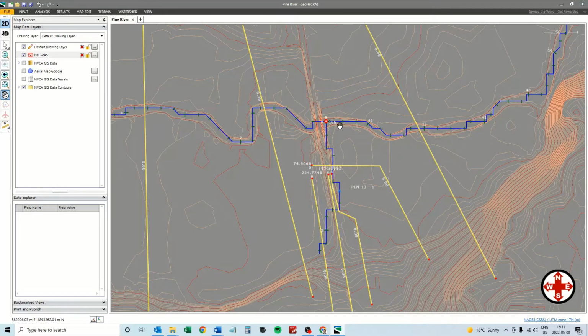Try to join these two, because I really don't need to know what's happening at this cross section, because I'll model the creek, and I need to know what the water levels are along this reach here, but I'm not really interested in what's happening on this little water course. The flow rates should still be maintained because they're assigned at this cross section here. Once these 2 reaches join up, the flow rate is indicated at this cross section, so that should not be impacted, but we'll see what happens.